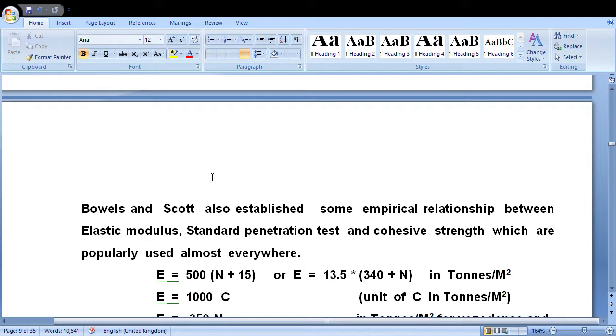In case of sandy soil, that is granular pervious soil, the immediate settlement appears to be completed during the construction work itself. In some cases, it is also noticed that while coming up to the plinth beam level, there is some amount of settlement for heavily loaded columns, and a very negligible amount of immediate settlement is generally noticed for slightly loaded ones.